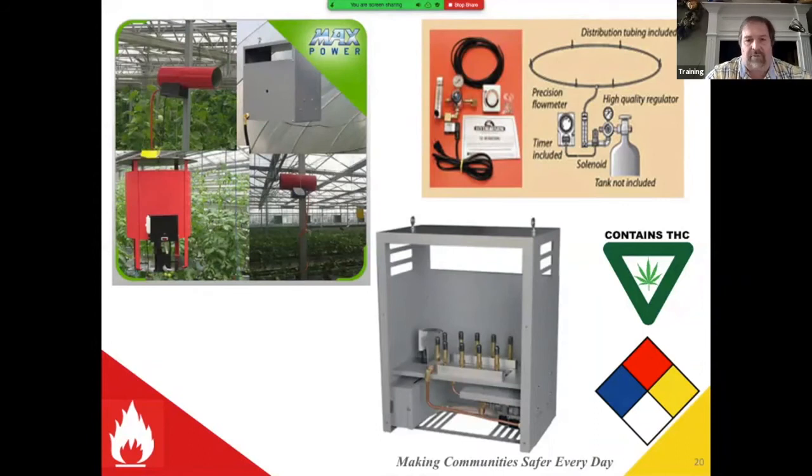There is a procedure in the International Fuel Gas Code that allows an AHJ to approve unlisted equipment. Typically, it does not require them to approve unlisted equipment. It's just an avenue if they choose to do so. Really, it involves still pretty much testing, almost to the same degree as a listed and tested piece of equipment. It's very detailed and very well documented. Procedures have to take place.